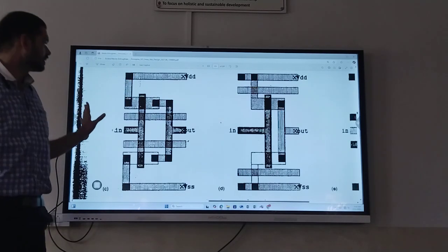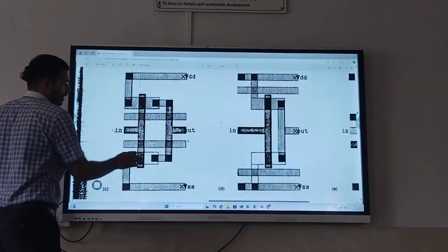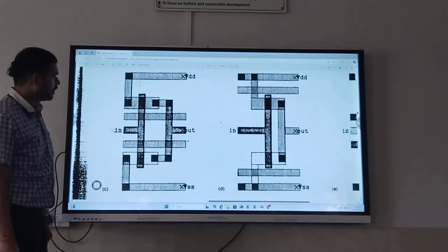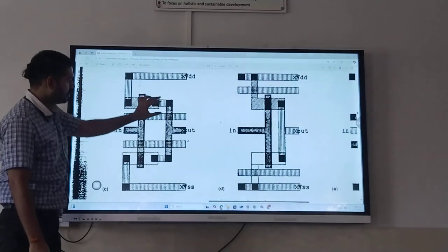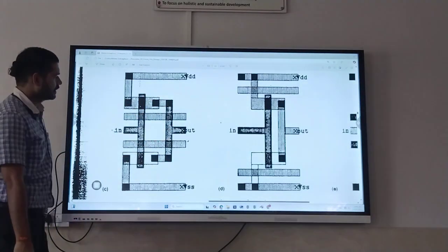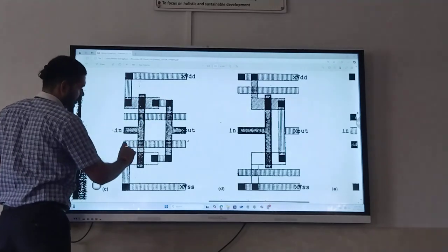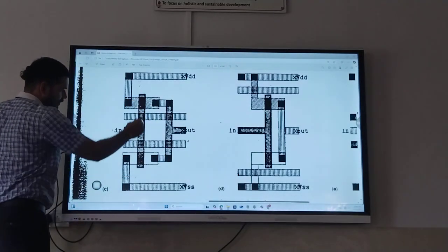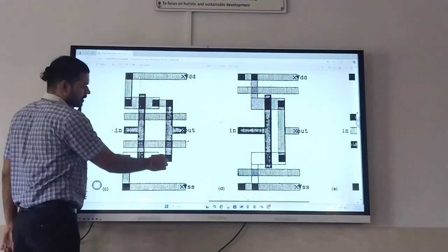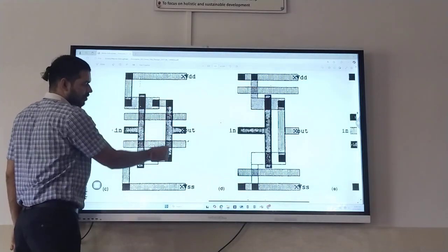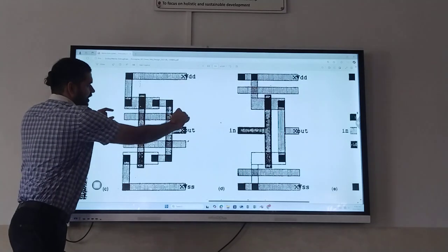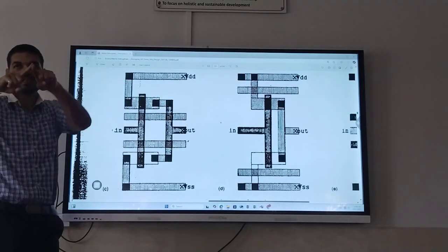In that case, what I can do is choose metal 2 here. See, actually this is field diffusion and diffusion, this is poly. And if I short the drain to drain with metal 1, then I cannot pass this metal with this metal, because both the metals will short.